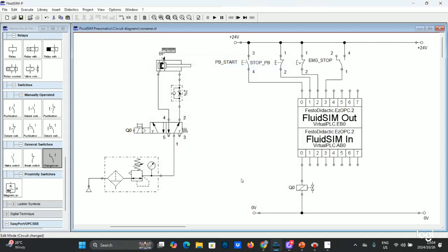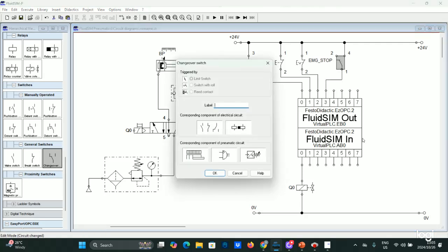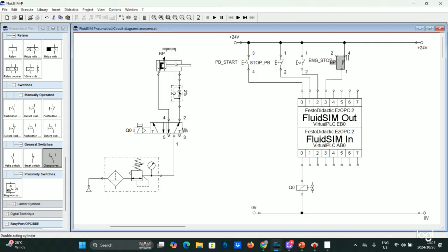If it's at 0 and 0, it means as you can see now it's currently at the back end. After we've added this, we'll also label our limit switch as the back position. Since our limit switch is currently in the back position, it's closed because it's detecting the back end position. You'll see when the cylinder advances, it's going to open up. Now, to fulfill the end condition,